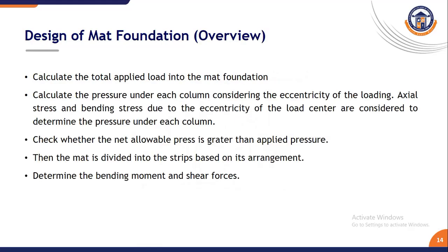Then design of mat foundation. Here the design process includes: calculate the total load from the structure and find the soil pressure under each column considering the eccentricity, and then ensure soil pressure does not exceed safe bearing capacity, followed by dividing the mat into strips or panels to calculate the bending moment and shear force. Finally provide reinforcement accordingly, both bottom and top. So these are all the factors to be considered for designing of mat foundation, right?